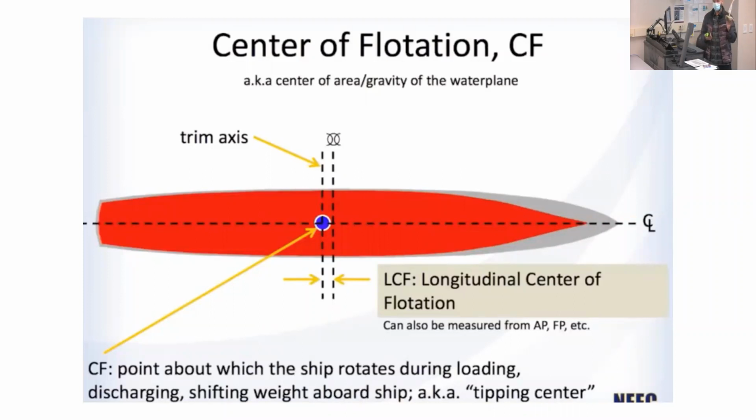So we do the same thing. If we have this funky object, which is not straightforward, we break it up into small boxes and do M1 R1 plus M2 R2 for those large number of boxes and divide by the total mass. Okay, that gives you the center of mass of the composite object. Is it making sense? Remote students, tell me if it doesn't. I'll repeat it. These are very basic things that need to be bulletproof.